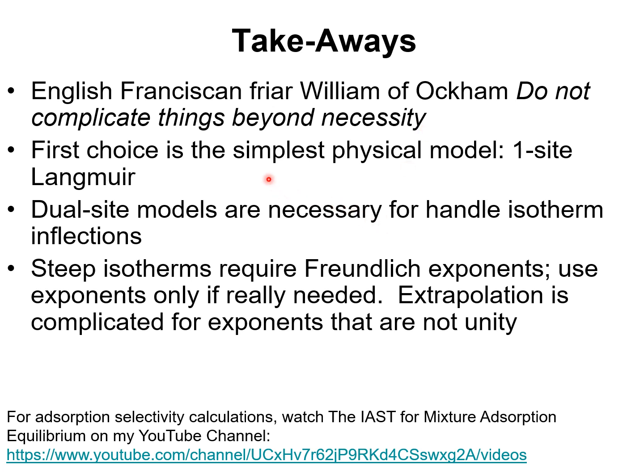We start with the simplest physical model, the single-site Langmuir model, and only resort to more complex models such as the dual-site Langmuir model or the dual-site Langmuir-Freundlich model if the unary isotherm data cannot be described adequately using simpler models.